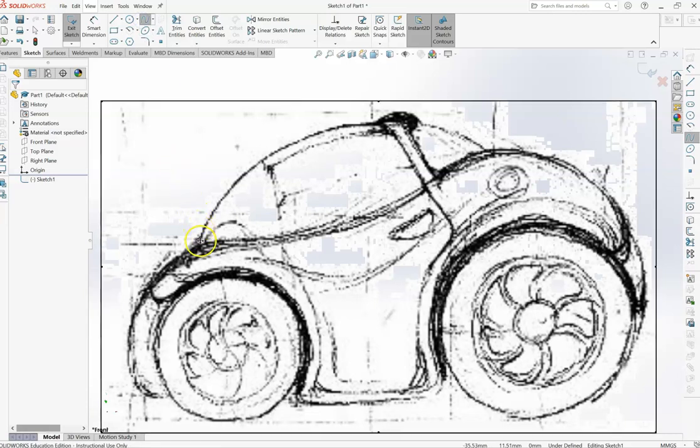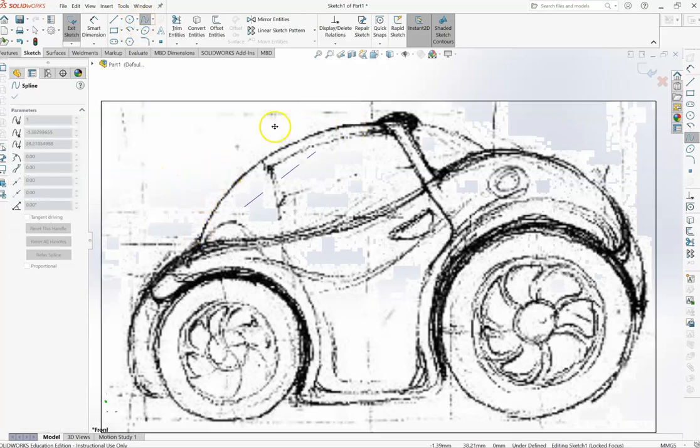Spline tool, starting from this point here. Okay, see how even though I can't see where I clicked, you can see that the spline tool is definitely working. Okay, so the spline tool does some automatic curving for you. Often it is really wrong about that curving, but we'll fix that up in a second. So I want to click here. I want to click anywhere there's a major change in direction. Here, over here, I want to click there.